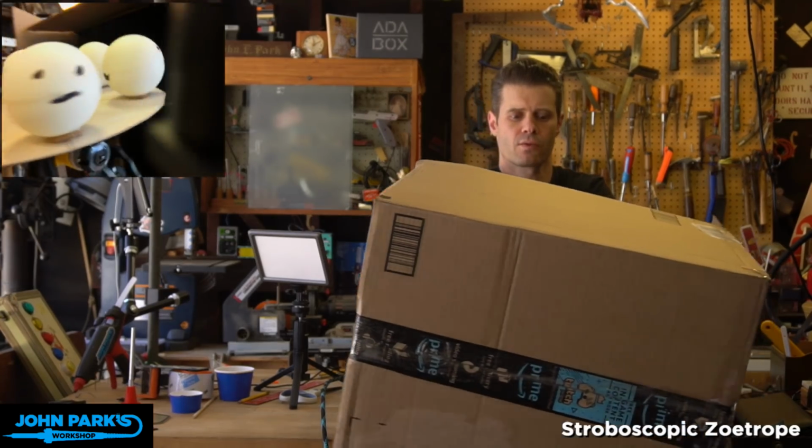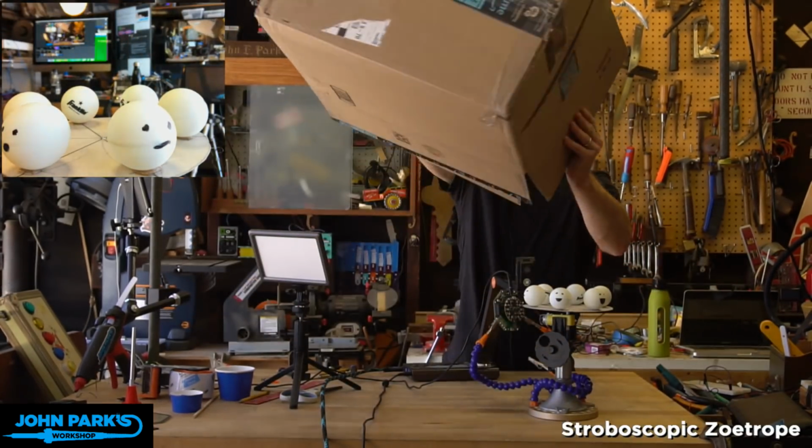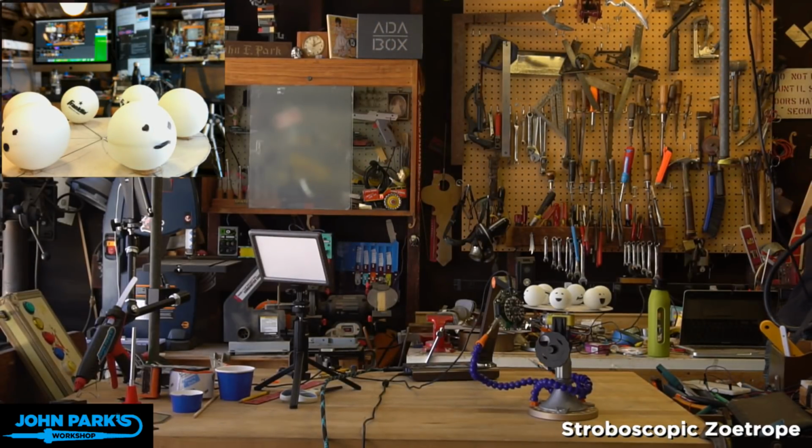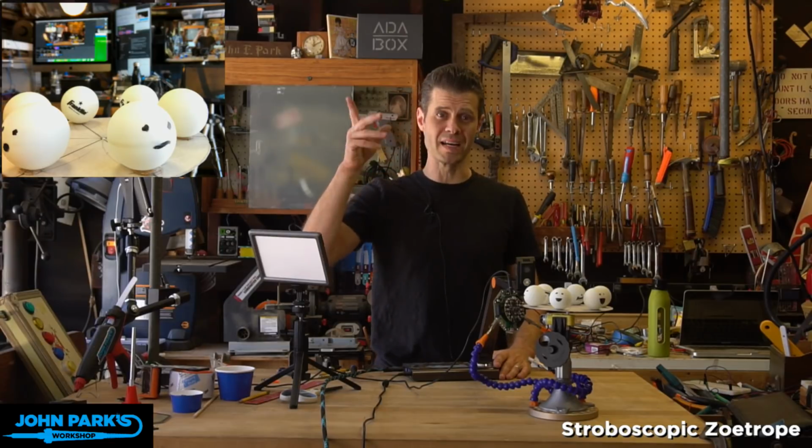Everything is going to be relative, of course, the size and speed and the rate at which you can blink. And I actually don't know what the theoretical or practical limit is of blinking the NeoPixels, but the way that I tried this was on Lady Ada's recommendation by using brightness. So you'll notice I'm not turning NeoPixels off and on, because that is going to take longer for the Circuit Playground Express to actually communicate to them versus the brightness control. That one just happens to be faster in this case.